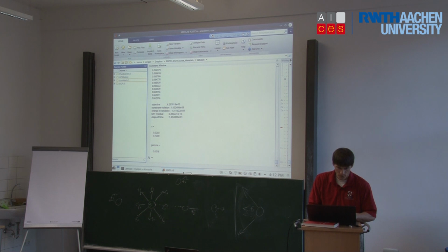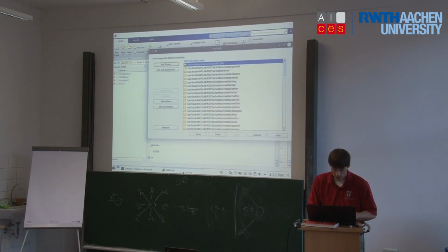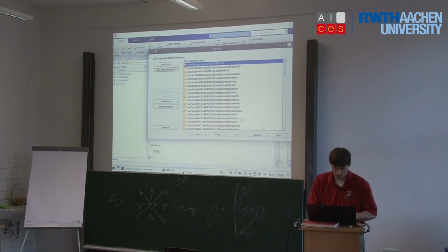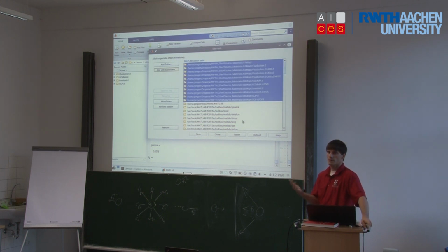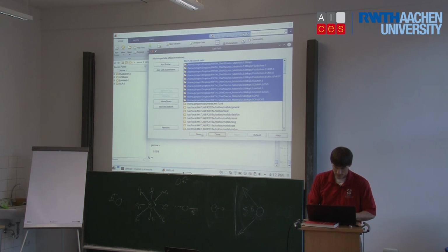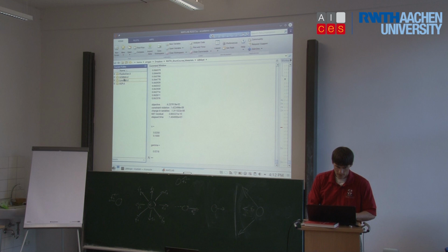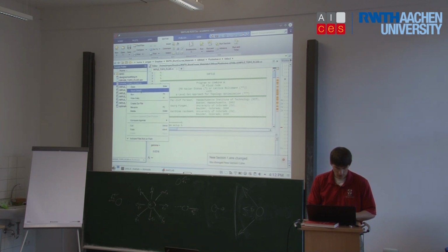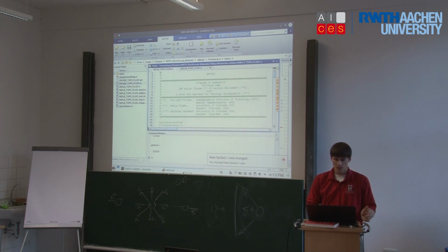So what we want to do first is we want to set our workspace, set the path, and so we want to add the LBM opt directory and all of its subdirectories to the Matlab path, which means that from anywhere within Matlab, you can now call the functions that are in those directories. Okay. And now we have 2 functions that we typically modify. The input file and the driver file. Okay. Typically, the driver file is where we execute the program. The input file is where we can make some changes.